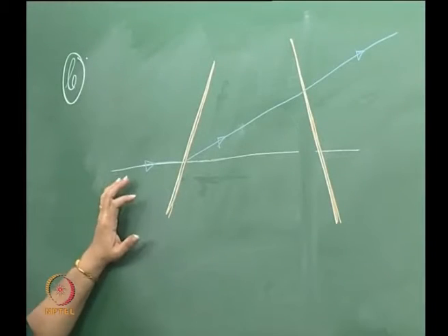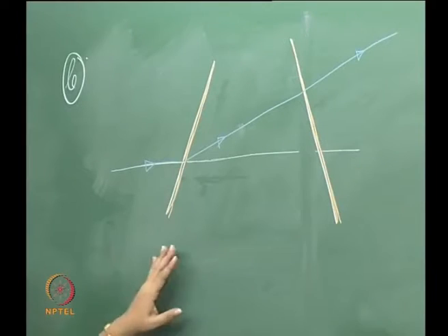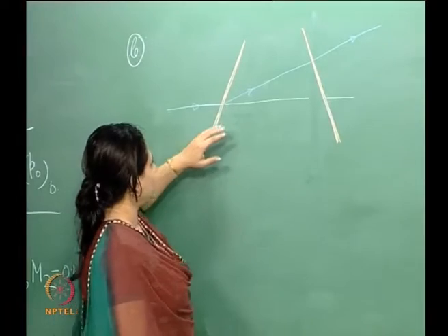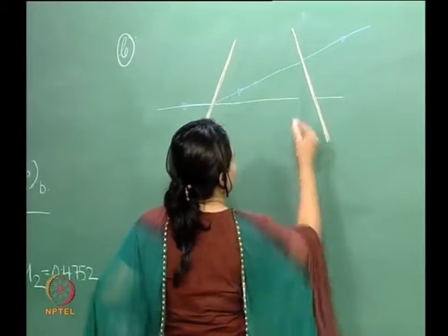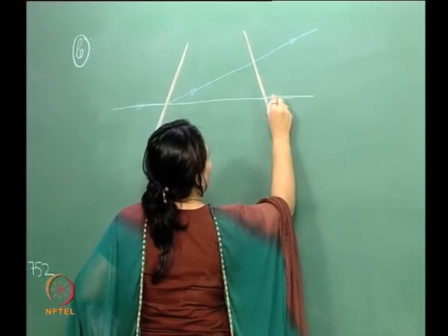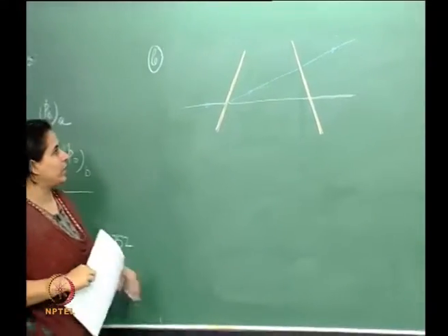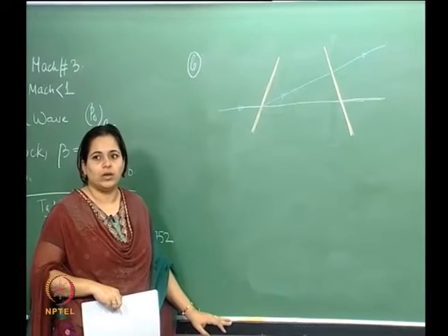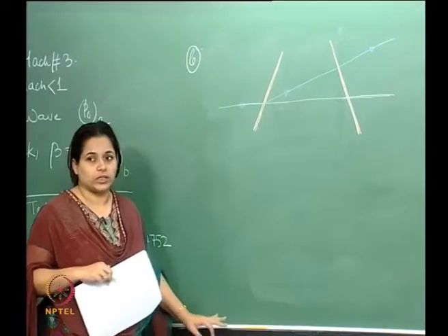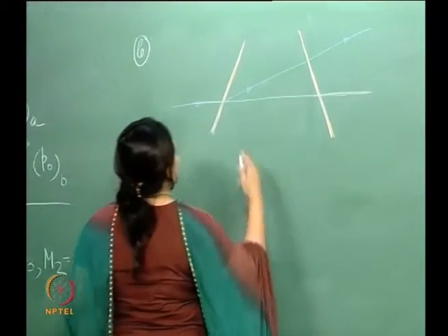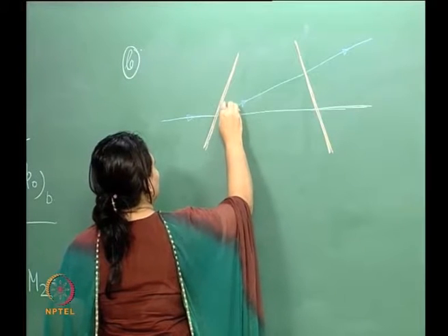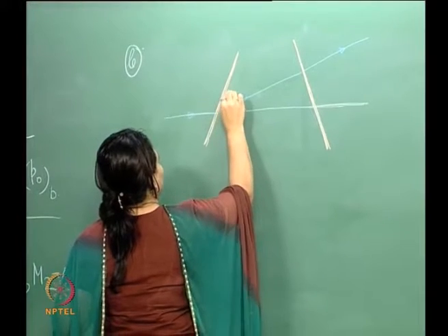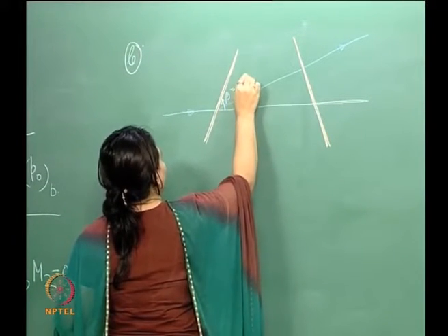Now what you have to understand, if you look at this, you'll be like, okay, both these are tilted or inclined. Well, these are inclined with respect to the horizontal, of course, but whether this is an oblique shock or a normal shock depends on the angle it is making with the free stream. In this case, this is the angle, beta, which is 40 degrees and is given.